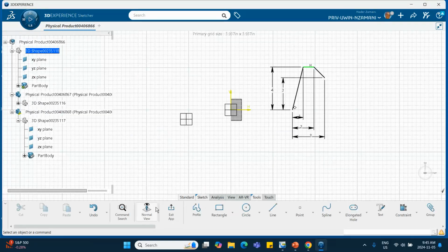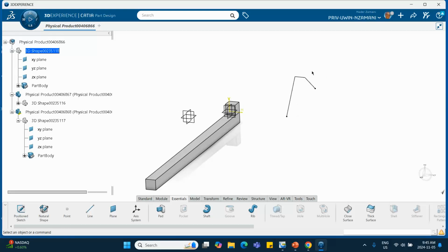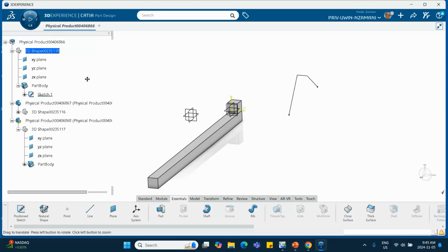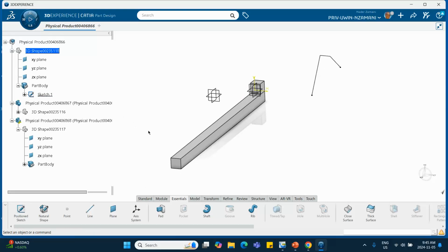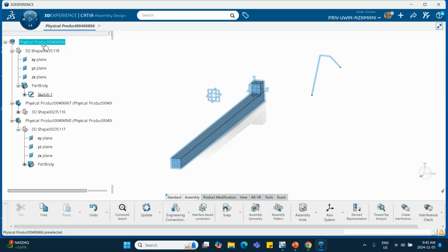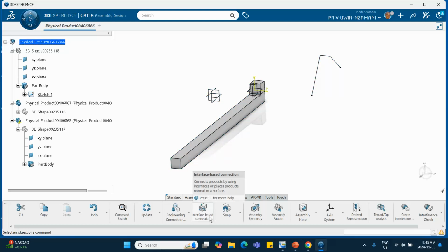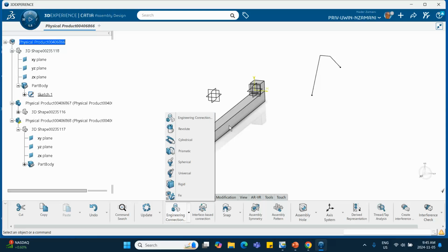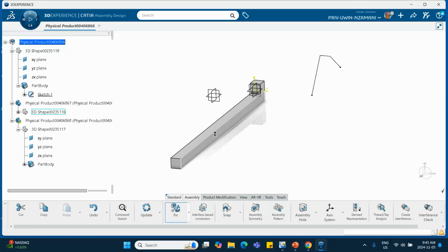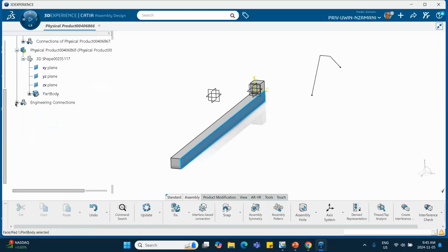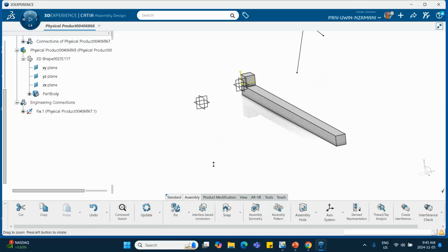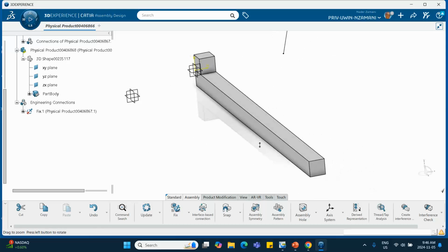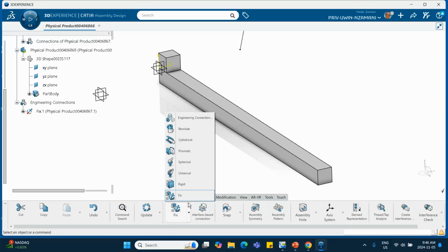Okay, let's go back here. This is all gone, exit. And notice that this sketch is created. It could have been anywhere. I decided to put it in the dummy shape holder right there. You can see that, it's right there. And fine. Now let's go back to the assembly right there, because I want to create my constraints, joints. So you go to engineering connection. First of all, let me fix that track. This is the track. Okay, it is first. It is fixed. You can see that. And then I want to create a prismatic joint. There's a prismatic joint.